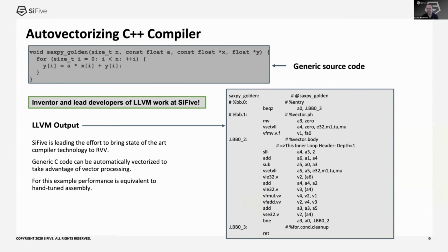Another thing that's in the ISA is, for example, a compress instruction, which can extract the non-zeros from a vector if you're doing sparse operations. So there's a lot of support for things you need in the AI algorithms, but it hasn't been highly tuned for a single specific AI algorithm at this point. We wanted a generic base that can run everything well as non-AI codes. There is a lot of other code, people might forget, but there is this other stuff we have to run apart from AI as well.